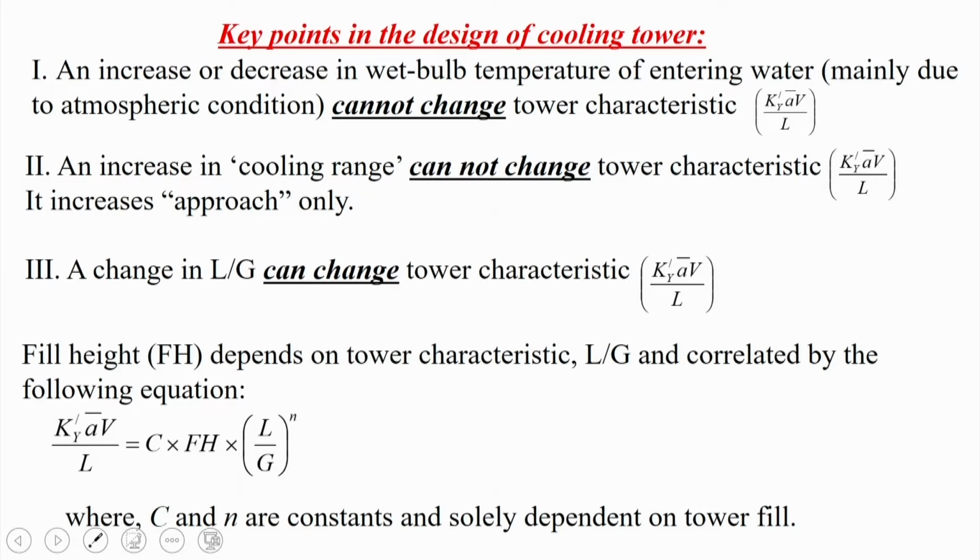Then an increase in cooling range cannot change the tower characteristic. It can increase the approach.